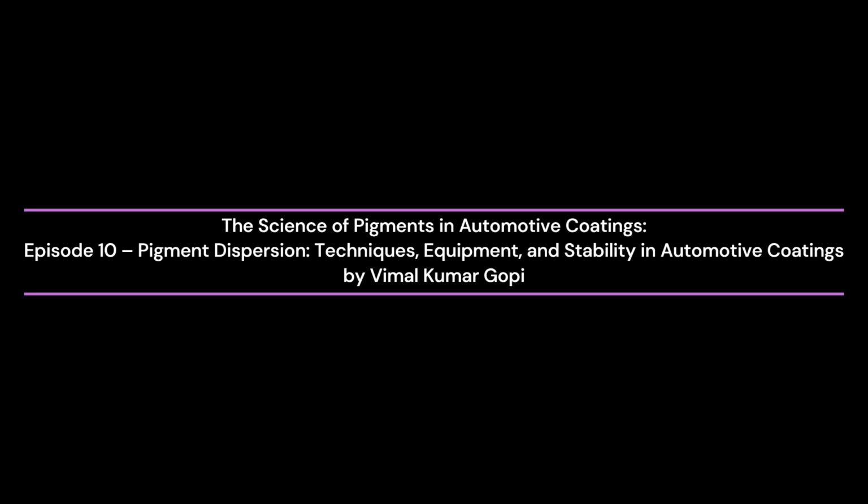Stability over time is another critical consideration. Pigments tend to re-agglomerate if surface forces overcome dispersant action, or if environmental conditions change. Formulators monitor zeta potential, particle size distribution, and rheological parameters to ensure that dispersions remain stable during storage, transport, and use. The binder system, solvent composition, and temperature also influence dispersion stability.